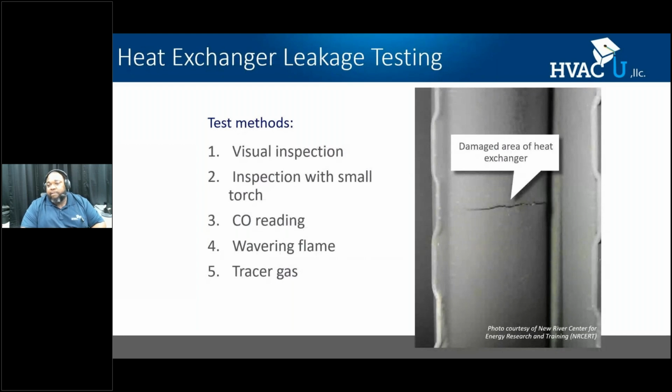Now, as a service tech for many years, I was always taught how to visually inspect for a crack, but I never really got the information to understand what was causing it. And a lot of times it was a poor airflow setup. Maybe the ducts were undersized, the equipment was too large. A lot of the stuff that we run into, we're taught how to find the issue, but we're not taught how to find why the issue occurred.